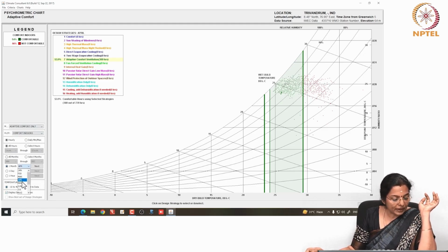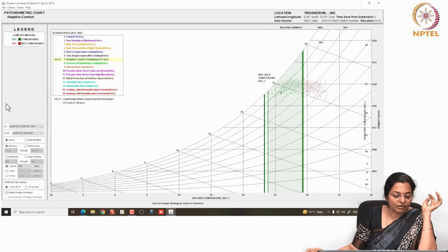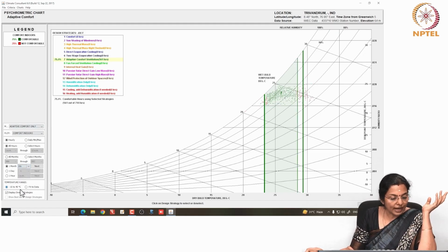What happens in May? In May, 55% of the hours can become comfortable if you follow adaptive comfort ventilation. Then June, what happens? 70% becomes comfortable just by providing good comfort ventilation. Then July, 75% of the hours.